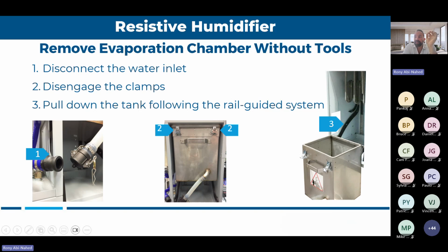But keep in mind, and that's really important, even if your water is not that bad, if you want precision of plus or minus 1%, you always need an RO system before the humidifier. And why is that? Because usually, if you're using city water, whatever brand you're using, your unit will go through a drain cycle every 4 to 6 hours, depending on how you program it. Why?